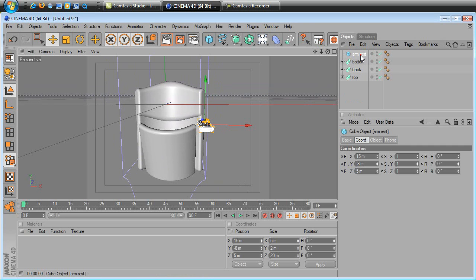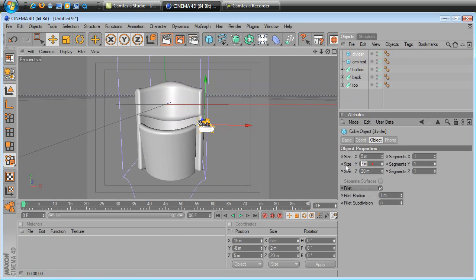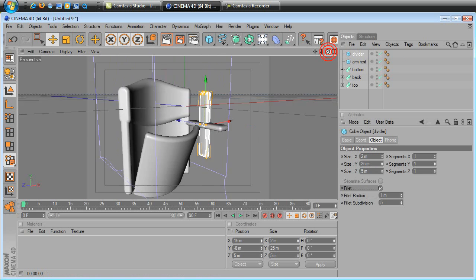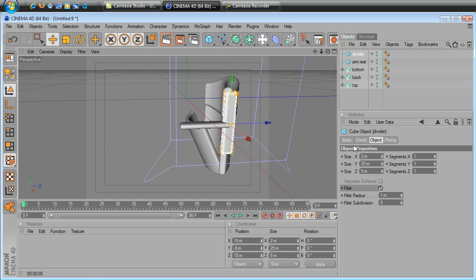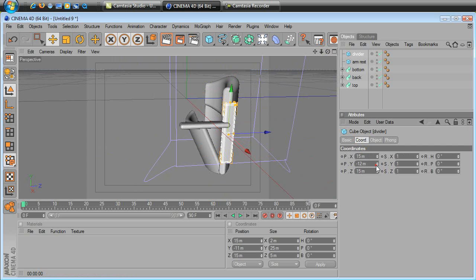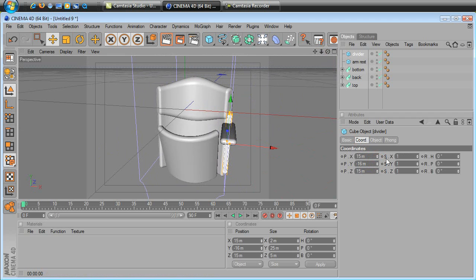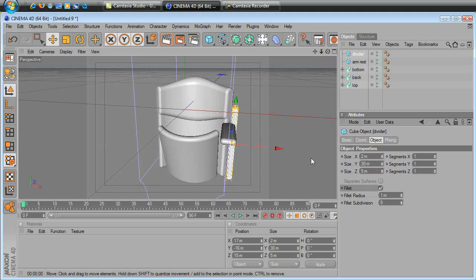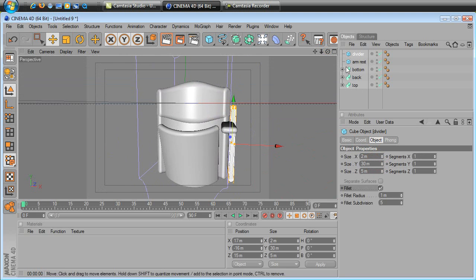And let's add like a little divider here. Just duplicate the armrest, call it divider. Change the dimensions to go higher in the Y, like 25 in the Y. Make it thinner in the Z, like a 5 or so. And thinner in the X too, to be like 2. So that this is just going to go between our seats a little bit. So let's slide this into place so that it's just something to define where one chair starts and the other ends. Let's actually make it taller, make it like 30. Yeah. And maybe a little thinner too.